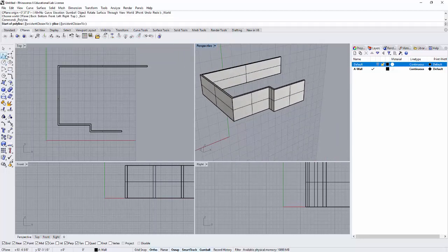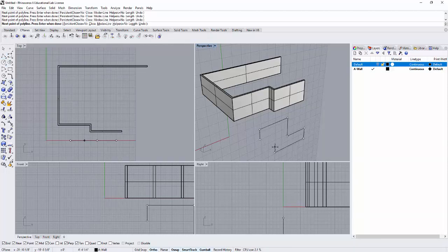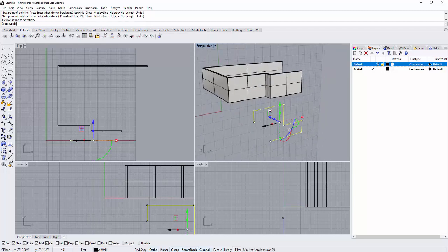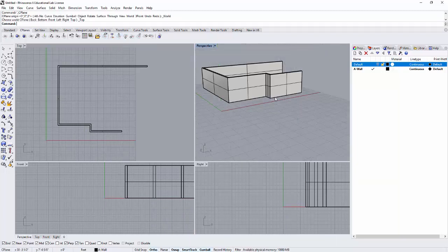So now if I go back to drawing a polyline, rather than drawing that polyline in plan view, it's drawing it in elevation view, which is handy, but it's not necessarily drawing it exactly where I want it. So I'm going to delete that, and let's reset it back to its default, which is top.